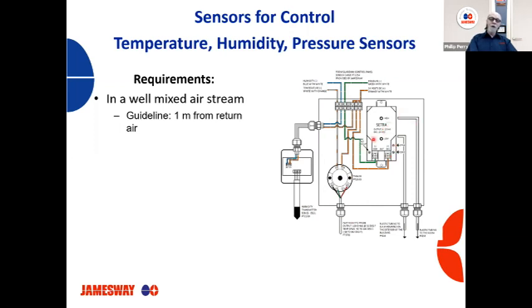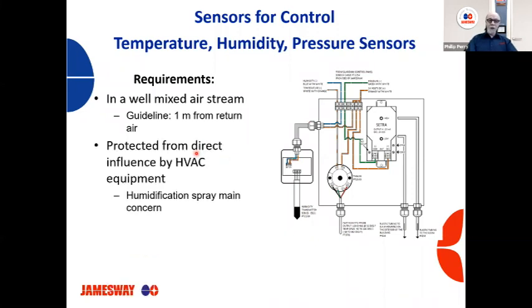So we want it up in the airstream in a well-mixed area of the hallway, protected from direct influence by any other HVAC equipment in the room. A main concern here is the humidification spray.